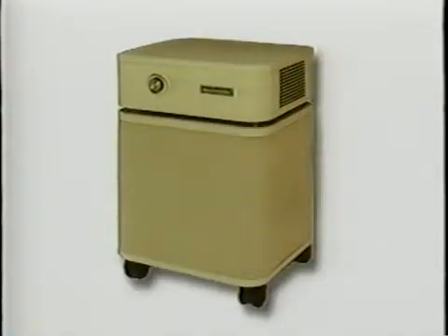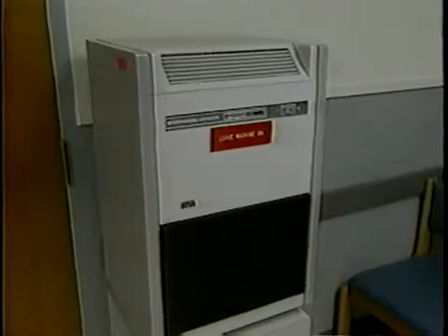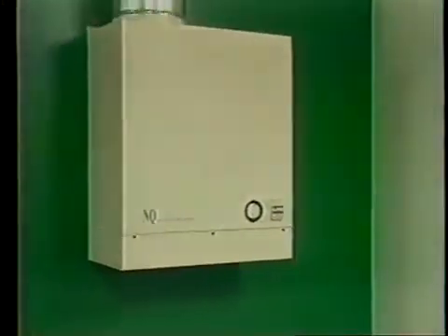These units come in a number of different configurations. The most common are small portable units that can produce 100 to 400 CFM. The larger portable units are rated for 150 to 800 CFM. Other designs include ceiling-mounted and wall-mounted units. The actual amount of air produced by these units is difficult to measure compared to a ceiling or wall outlet, because you can't just put a flow hood up against them.